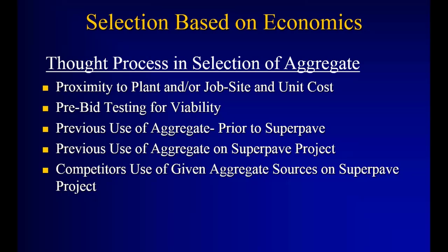Is it in Grand Forks District? Is it in Williston District? Is it in Bismarck District? That plays a lot, obviously, because you have to look at this kind of delicate balancing act of how good are my local aggregates. Of course, the more local the aggregate, the cheaper it's typically going to be to haul.